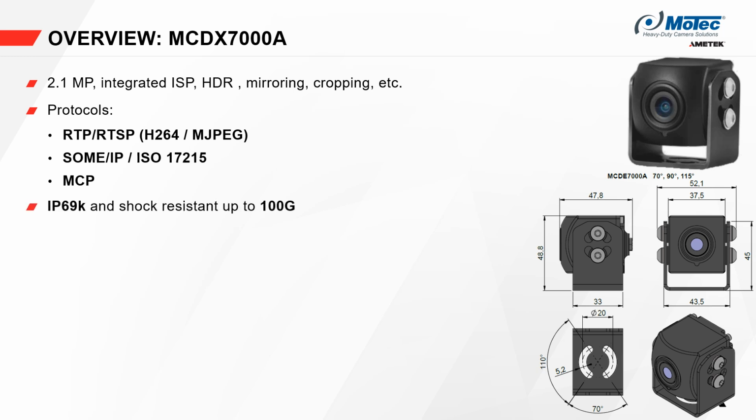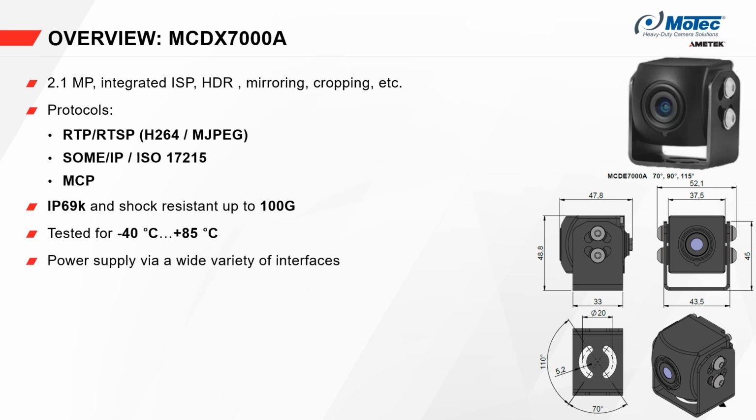The entire device family is IP69K rated and shock resistant up to 100G. This allows the camera to be used in even the harshest of environments in the agricultural, transport, construction, or stationary industries. We tested the camera to work reliably between -40 to 85 degrees Celsius ambient temperature, which should fit even the highest demanding in all your applications. The camera can be powered by a wide variety of interfaces, which we will learn more about in the slides to come.